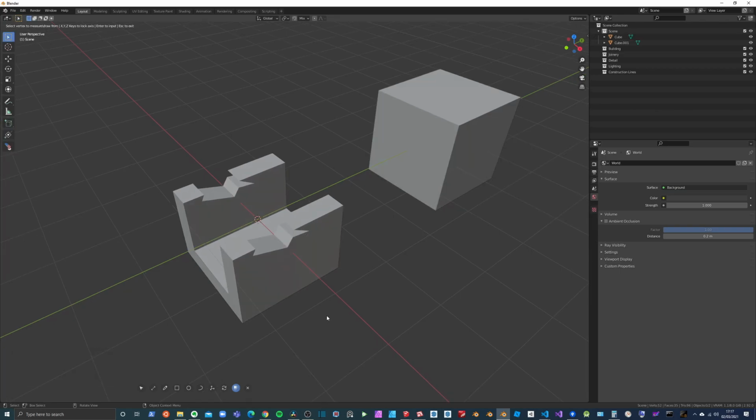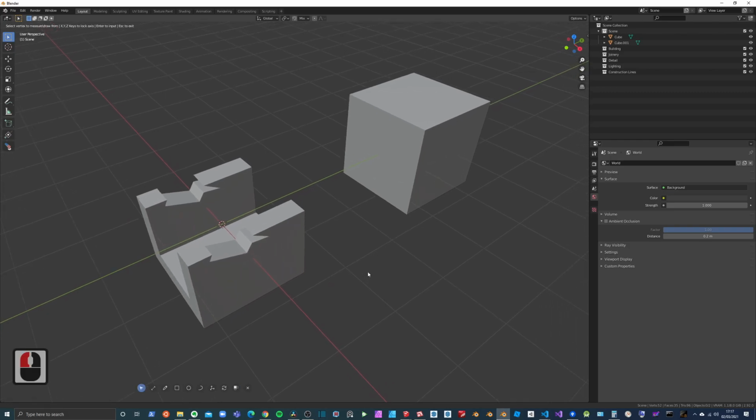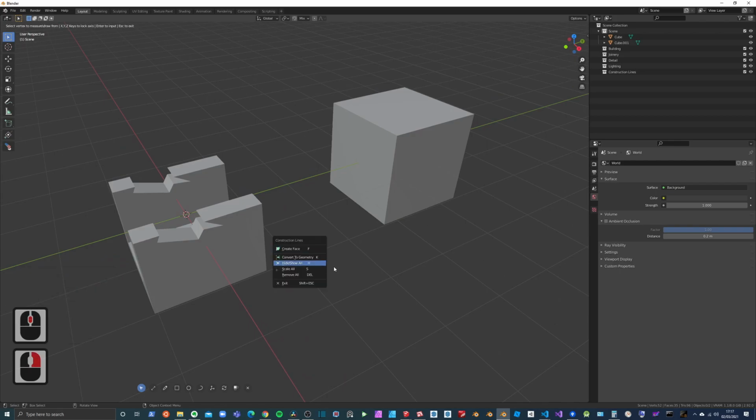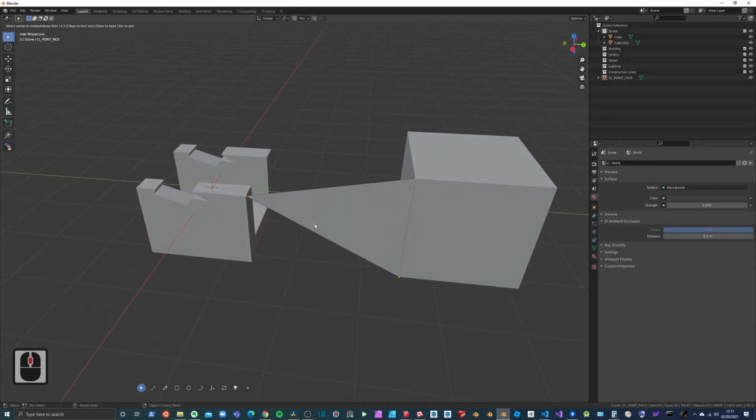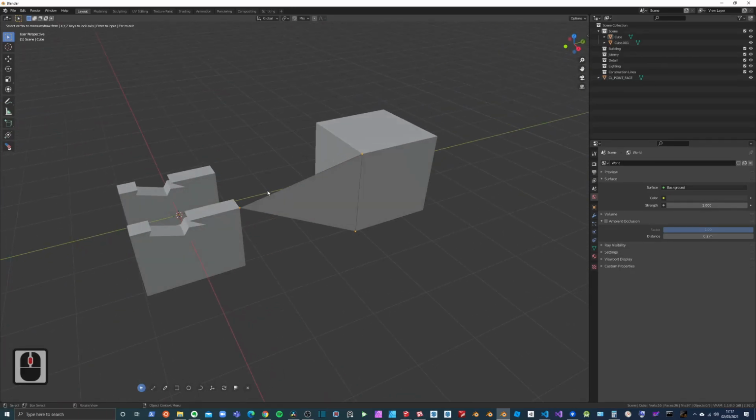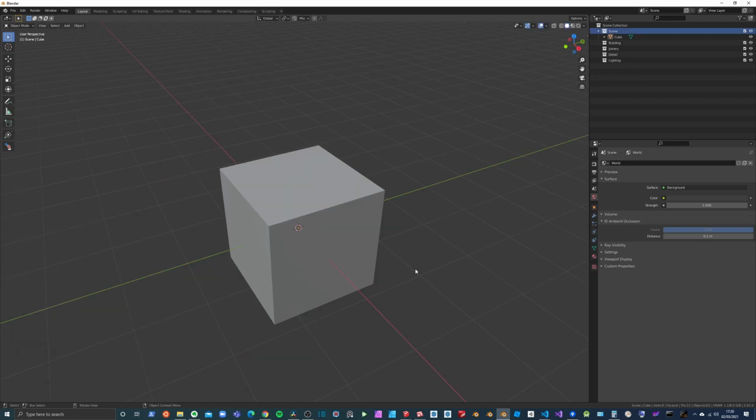The final feature or change that I want to talk about is the face creation, which was a feature before. It's still in the context menu, but the way you select the vertex points is slightly different. Now in select mode we hold Shift and Control, and then we can select the points that we want and either press F or click Create Face. So it works the same way, it's just slightly different in the way you do selections. There's a couple of known issues.